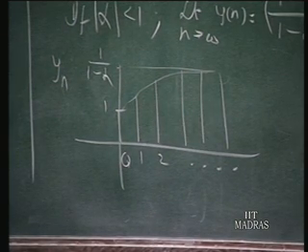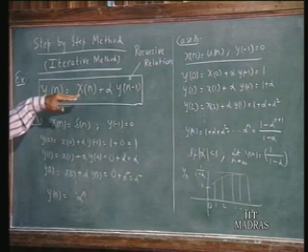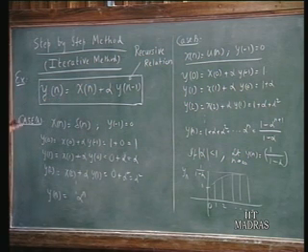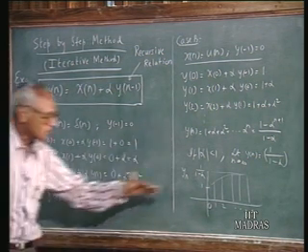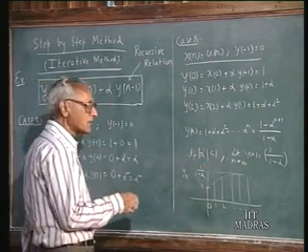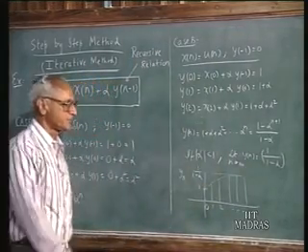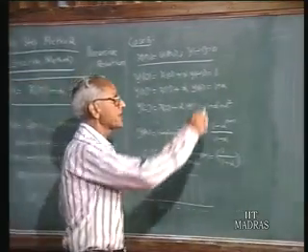See, in this difference equation, yn minus alpha yn minus 1, the first order equation has only one root of the auxiliary equation, which is equal to alpha. So for stability, the magnitude of alpha has got to be less than 1, so it builds up like this. If the magnitude of alpha happens to be greater than 1, it may turn out that this becomes very large, it may increase like this.